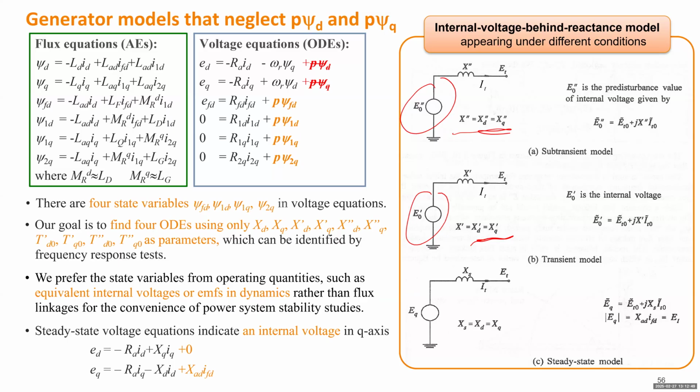The transient dynamic has not started yet, and the system has not gone to the steady state. So they only use the first model, which has the same structure as the steady state model. It just connects the first model to the network and solves the power flow. That will give you an estimation of the fault current.